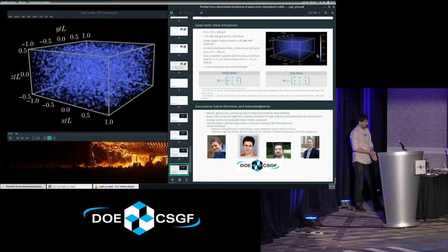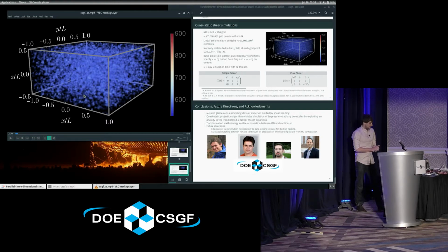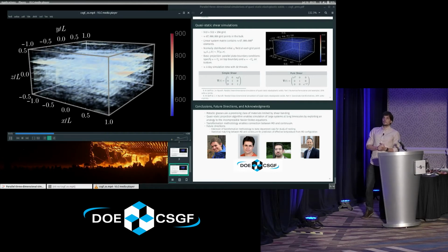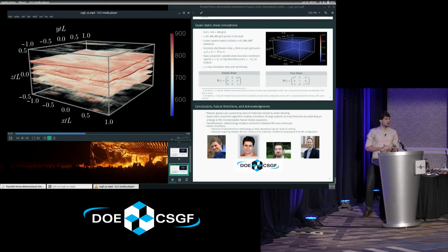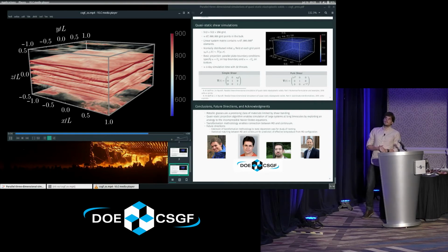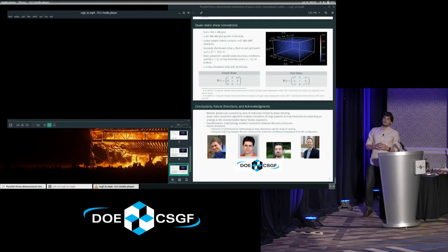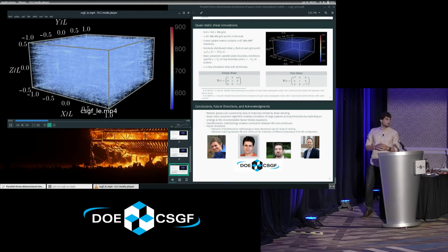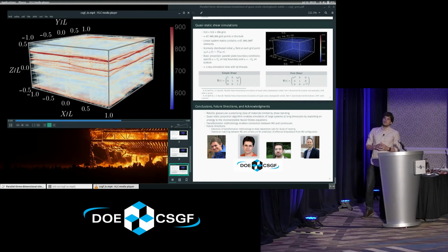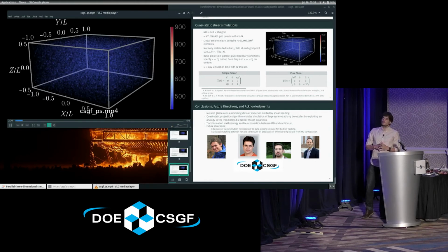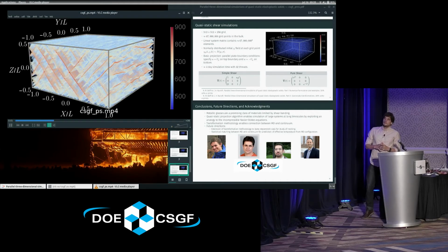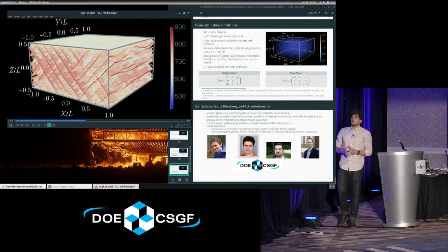the basic simple shear projection, no transformation here. This is the effective temperature field that we're visualizing. So you can see shear bands form in the effective temperature field. It's a proxy for the amount of plastic deformation occurring in a given location. This is the Lees-Edwards simulation. There's a preference for vertical connecting shear bands to form in Lees-Edwards versus basic simple shear. And then this is pure shear, where you can see all these nice diagonal shear bands forming and propagating across the material. So I'm just going to leave these running in the background.